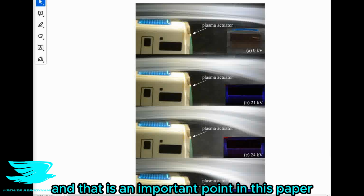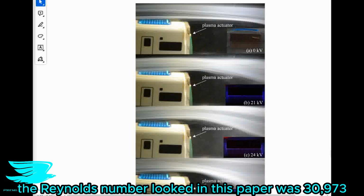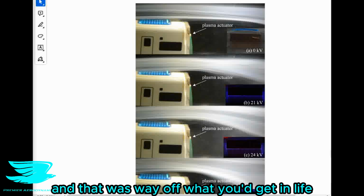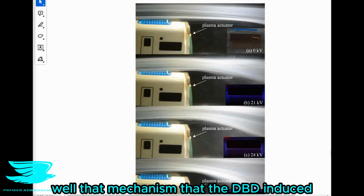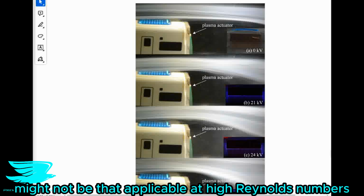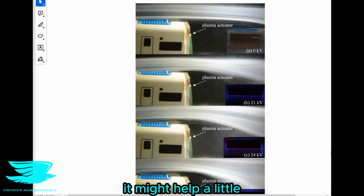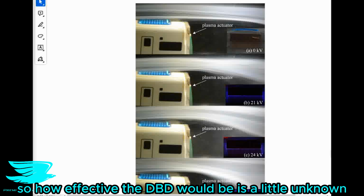And that is an important point in this paper because remember how we were saying that the Reynolds number in this paper was 30,973, and that was way off what you'd get in real life of maybe like 5 million or even higher. Well, that mechanism that the DBD induced at the front of the train, where it re-energized the flow, might not be that applicable at higher Reynolds numbers. I mean, sure, it might help a little, but the flow is already traveling really fast, so how effective the DBD would be is a little unknown.